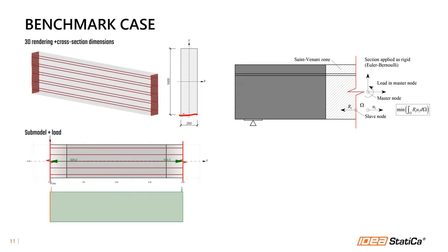This is basically the submodel. So I was utilizing the submodeling approach where, as you can see, I have some so-called non-analyzed zone or some trimmed end, where the simulation is not running. It's basically like a rigid zone. So the simulation here is not displaying, and on the left side it is displayed. So this area is basically analyzed, and the area on the right side is providing you the correct load transfer into the submodel where we need the results.